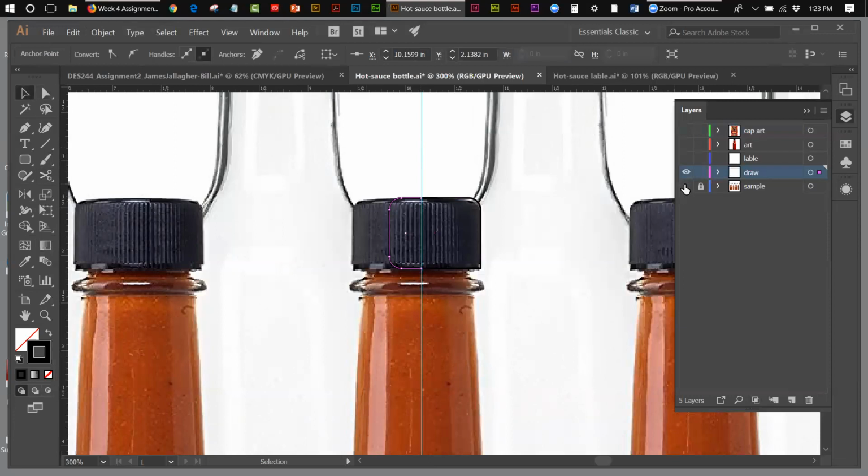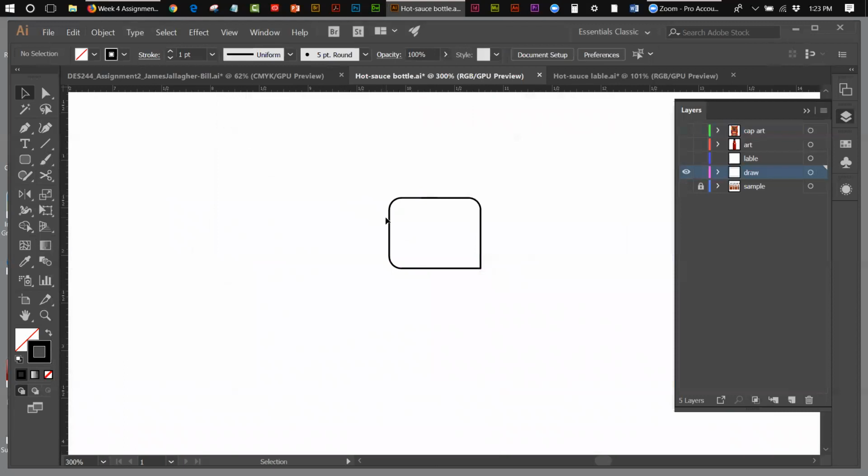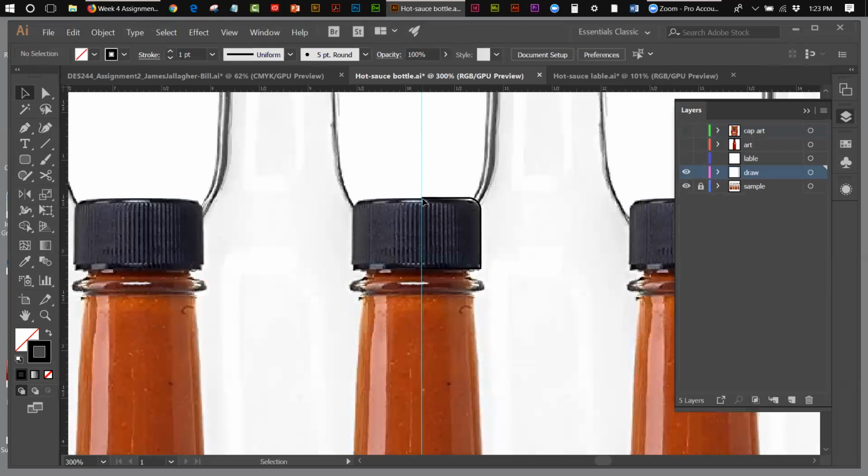And now what I've done is this. Watch. I'm going to hide the shape. Watch what I did. I click on this, and I hit delete, and I've actually cut this shape into an open shape, okay? That is what I'm looking for. That is the shape that I am going to use to create the cap of my little bottle, okay? And I got it from here. See it? I've just basically more or less copied the shape that's there, okay? And I only need half of it. I need what's known as a profile.